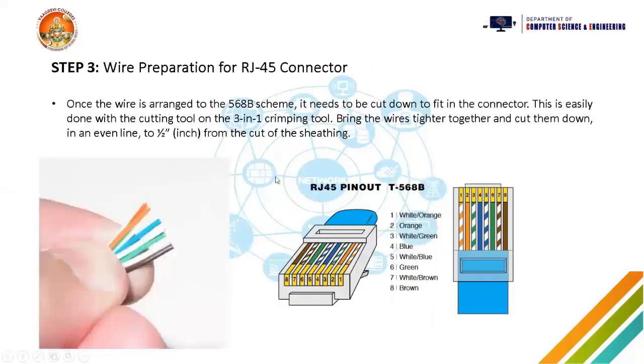Next, before inserting, we have to make sure that we keep all the wires aligned at the same height, and when inserting we have to make sure that at least half an inch of the wire goes inside this pin and touches the bottom of the pin. That's nothing but a shield.